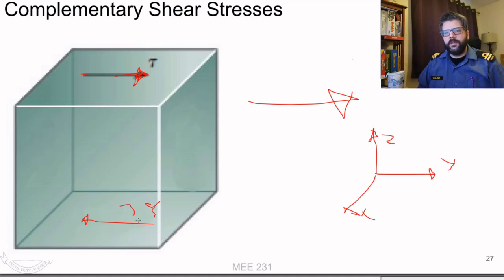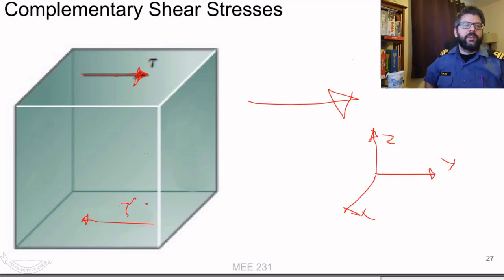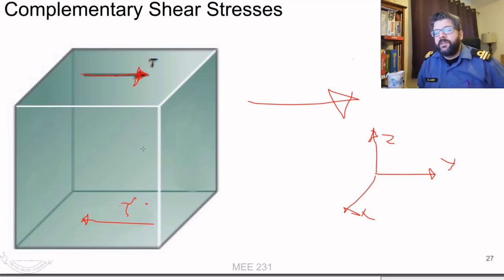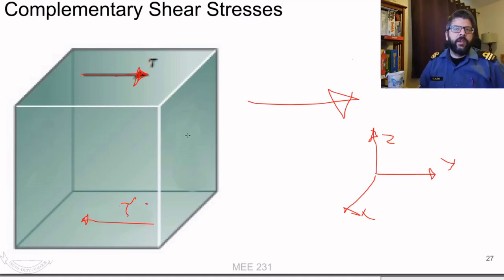And that looks a bit like a tau. There we go. So equal and opposite. But we're still not in equilibrium here, are we? We've got the sum of the forces in the y direction balanced out, but now we've got a moment couple. If we just left that as is, this thing would just start spinning and spinning, and that's obviously not actually happening. So we need some sort of reaction that occurs in order to counteract that moment.